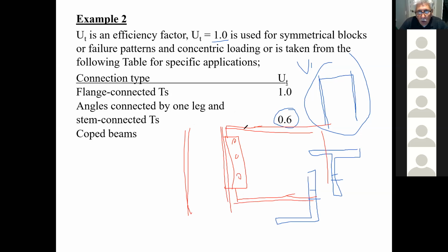Now, if I do a section across here, I'm going to try to draw you a section. So this is a section of the column. Here's one angle here. I won't draw the whole thickness. Here's another angle here. Basically, the web of this beam has to drop in here.